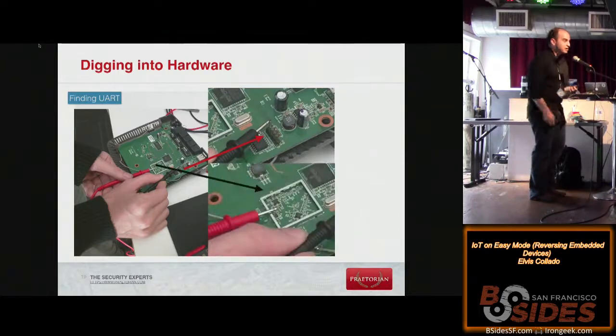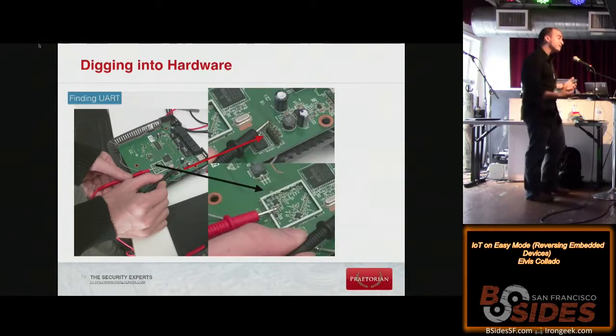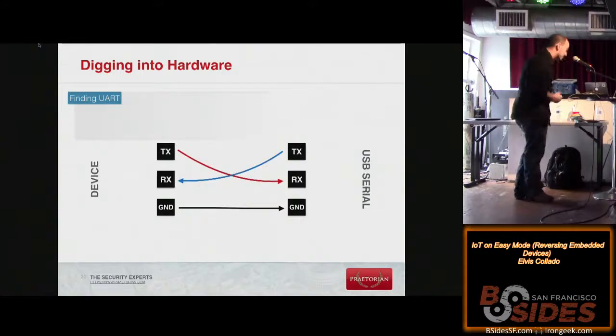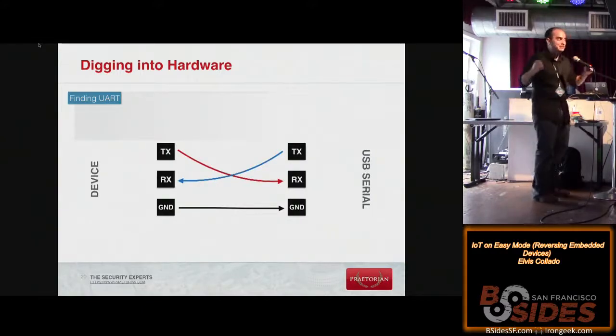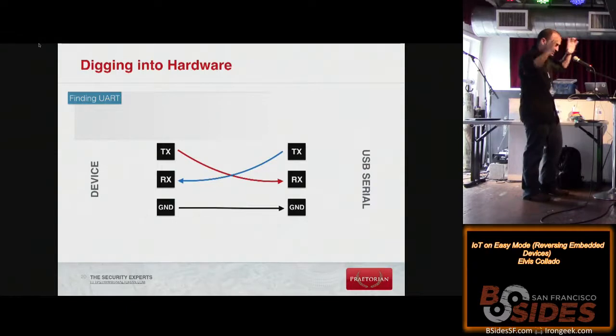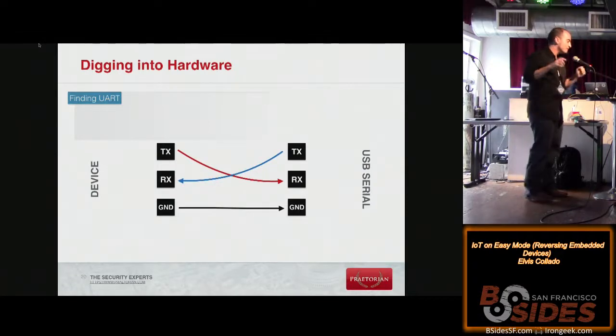So this is a common ground that I found out as well. Not everything uses ground like this, but it's a good start, right? So once you find ground, remember, connect ground to ground. Never put +5 or +3 or whatever into ground. It's something I'm still kicking myself about. But this is high level stuff. This is just how it works.